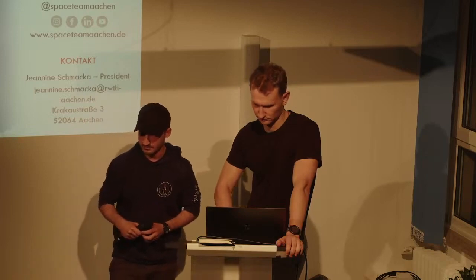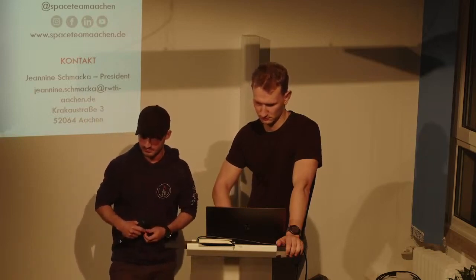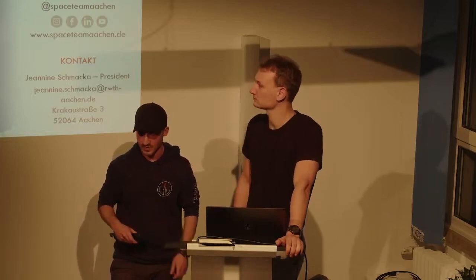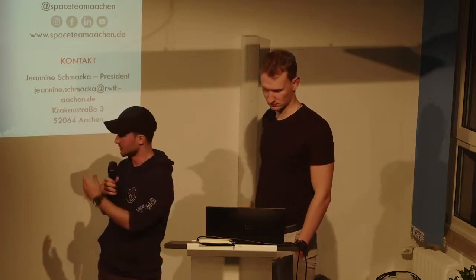Yeah, the nose cone is higher than the rocket body, so the shock cord is just shorter. And when they descend, you have the rocket, and you have the shock cord, and then the nose cone, and then the parachute. So it's one after another, not side to side. One problem that is obvious is that the cord is on the nose cone, so it wiggles around when it's in the air, but that is what we are going to test in the structures test campaign, what Janus already said.